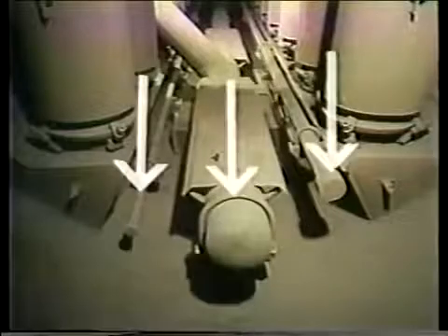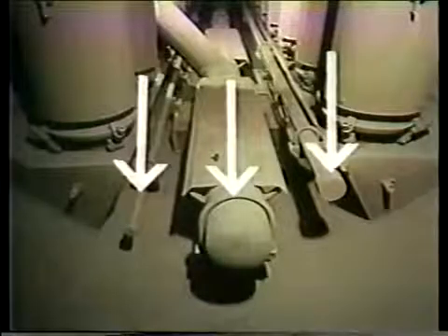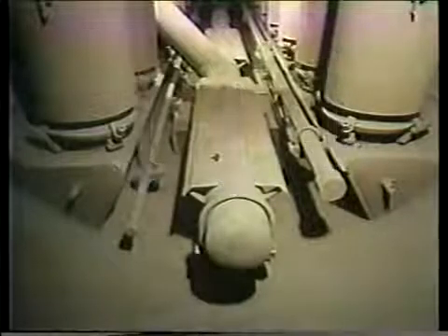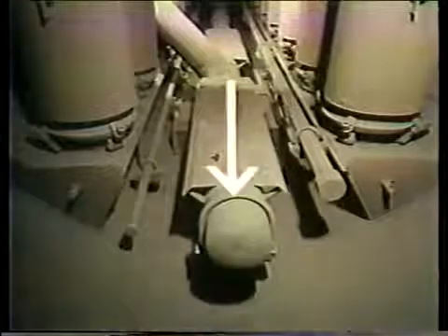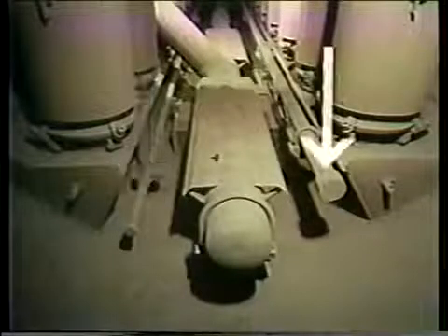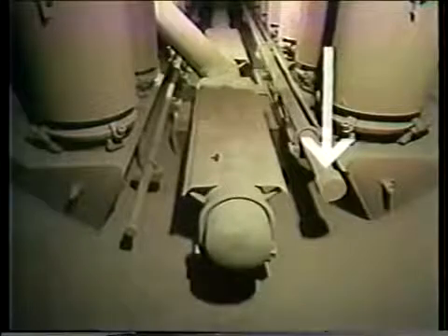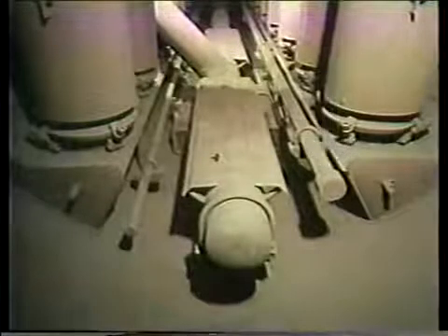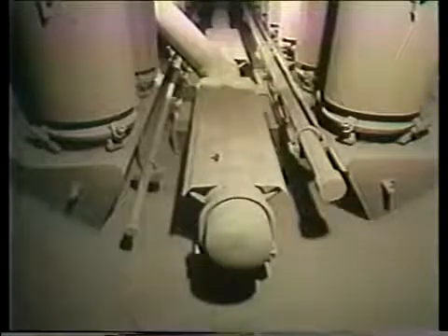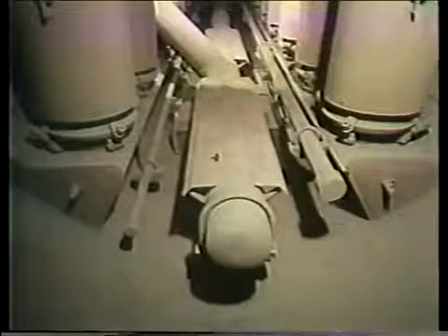Distributors are another internal feature that must be inspected. Distributors are pipes with holes in them that run along the length of the drum. A steam drum usually has 3 of these pipes: the feed water distributor, the chemical feed distributor, and the surface or continuous blowdown line. All 3 are located below the normal water level. While they look about the same, their sizes vary.